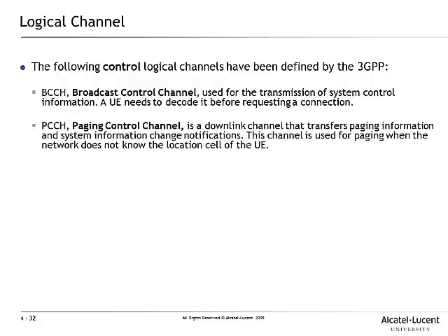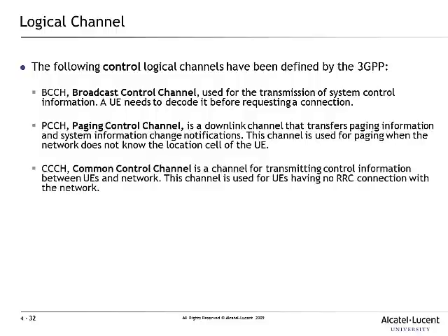And the next type of channel that we use is for paging. Paging is used when the network wants to know the location, at cell level, of a UE; we have paging messages being sent on the paging channel. Again, it's a downlink channel. You never page on the uplink. The third type of channel that we have is the common control channel, CCH. For those of you who've done GSM or 3G, you know that these terms are all familiar.